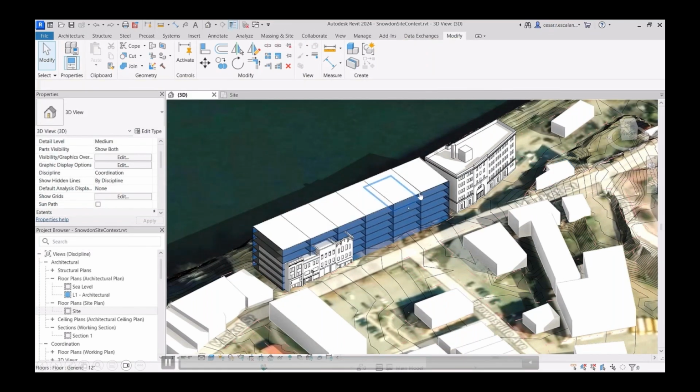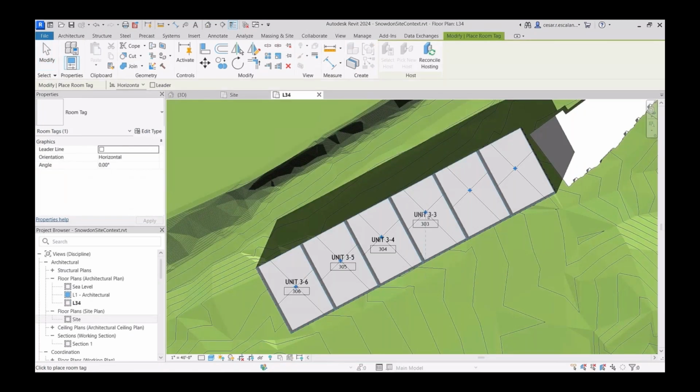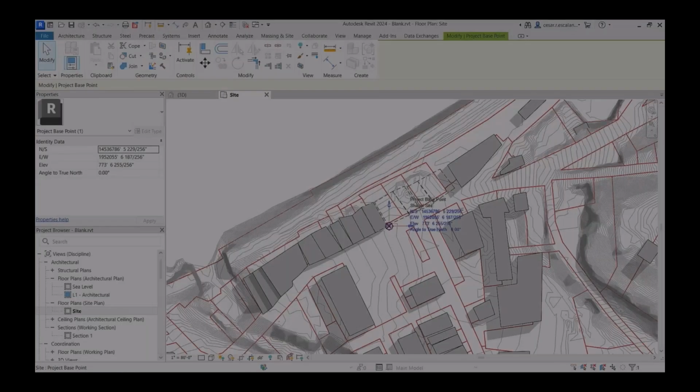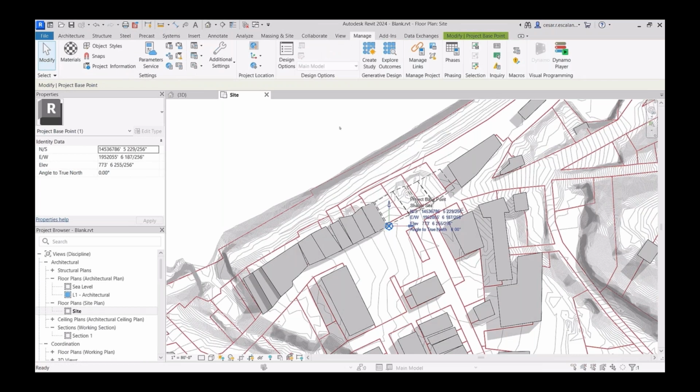It's not only that, you can also annotate with those details, for example, this is unit 1, unit 2, unit 3. You can tag with that, and it also gives you the exact geo coordinate locations of the particular topo surface. Since we are accessing the project data from the map, it gives you the exact coordinates of the surface which you have loaded into Forma. That same coordinate will be accessed here inside the Revit platform.